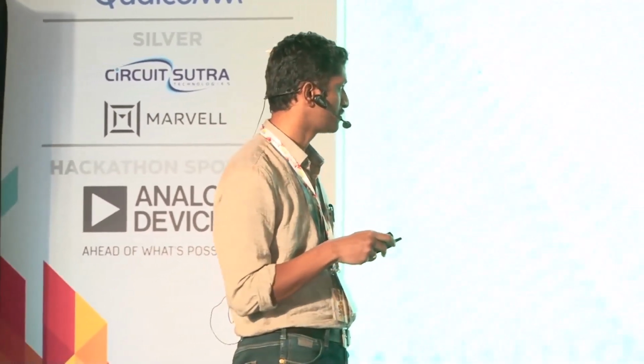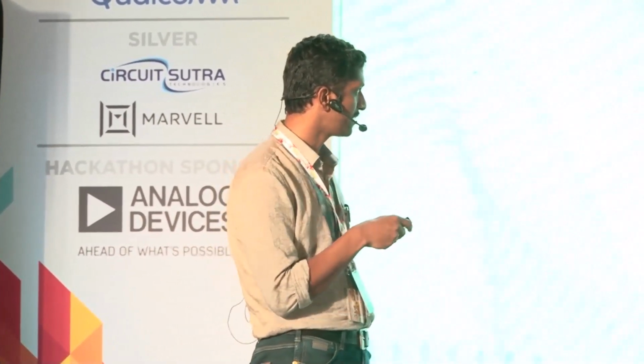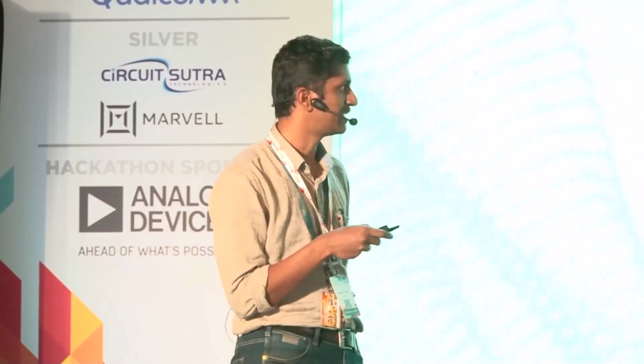Whatever possible scenarios there are, the tool will try to extract them. But as a designer, I know which scenarios are valid and which are not. So to restrict the properties, I write assumptions. If you are familiar with the formal flow, we write assumptions so that we can restrict the tool behavior. Then I rerun, analyze the results, and debug.